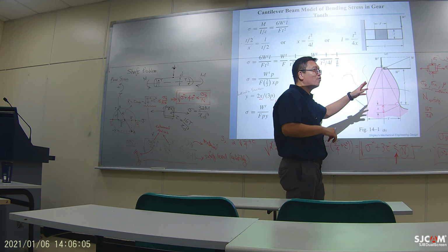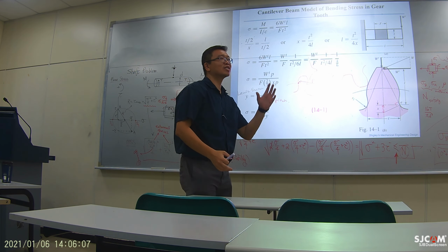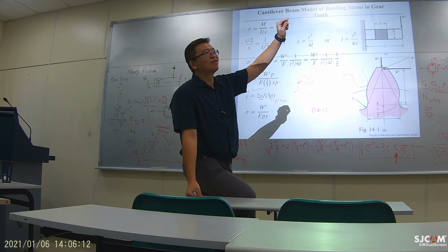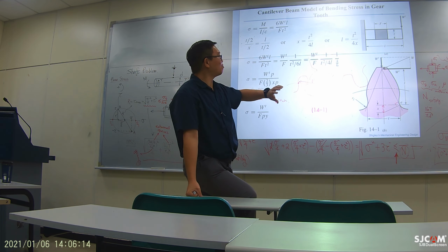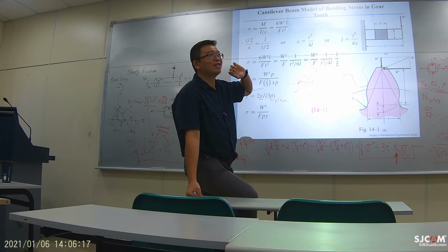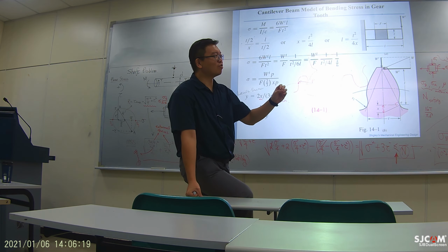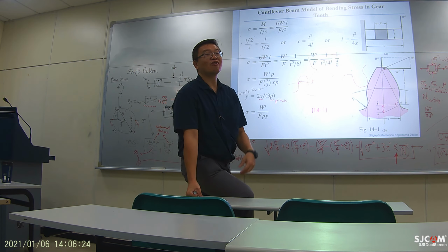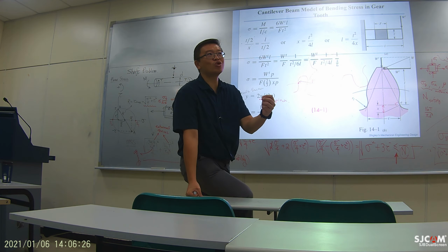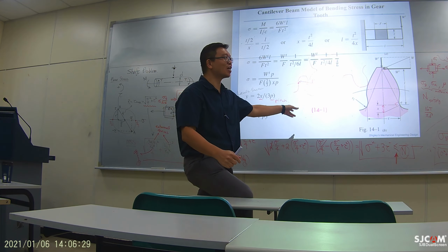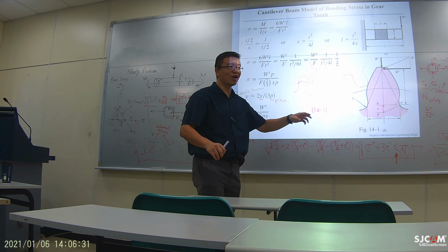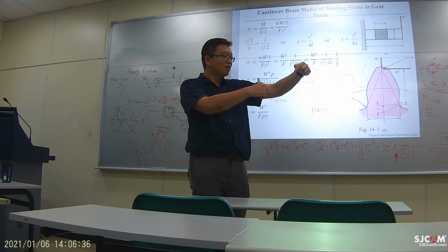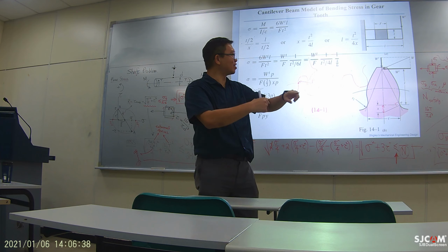So why do we study this particular moment? Because at this moment, the external force coming from the other side is going to generate the most stress for this particular tooth. For mechanical design, we care about the worst case. We don't need to study other conditions where the force comes from the other side but is not applied at the tip.